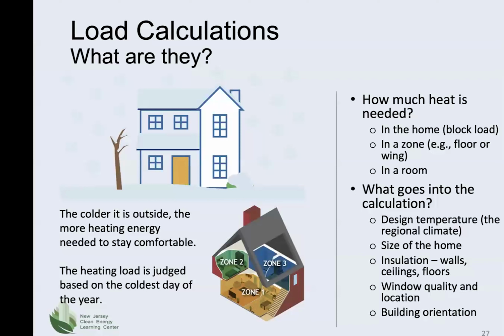Each individual room is going to have a different heating requirement based on the size of the room, the R-value of the exterior walls of the room, the quality and size of the windows and exterior doors, the air infiltration, the orientation of the house, solar gains, etc. These are some of the many factors that go into the calculation of heat load.